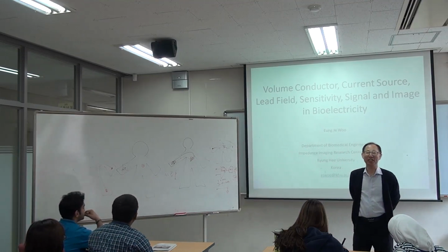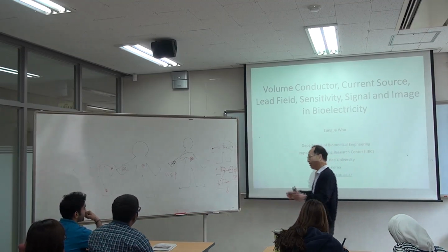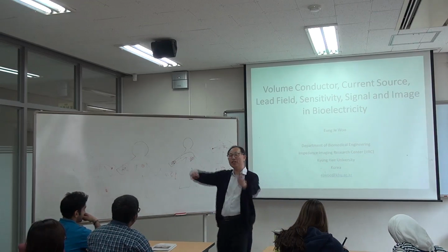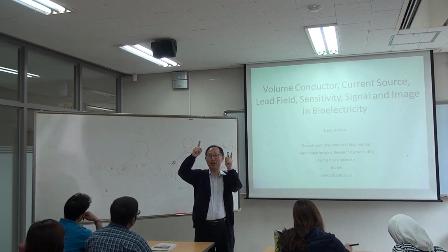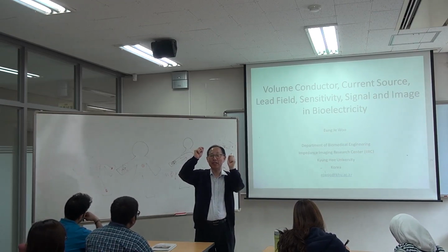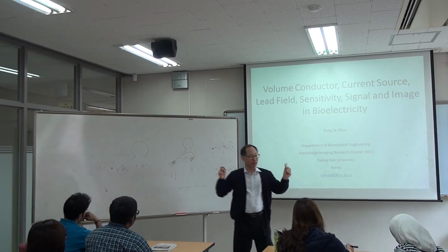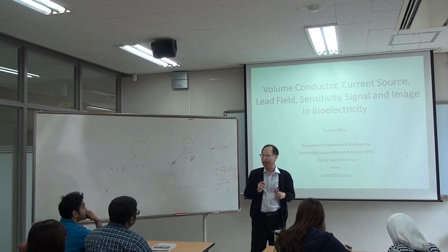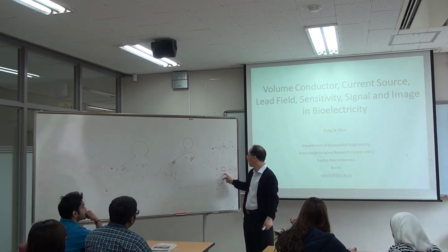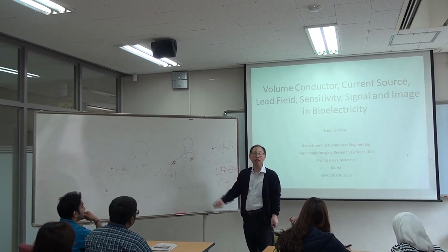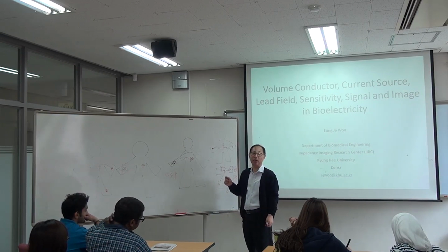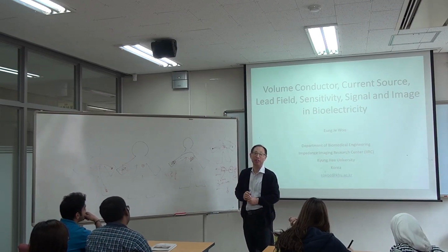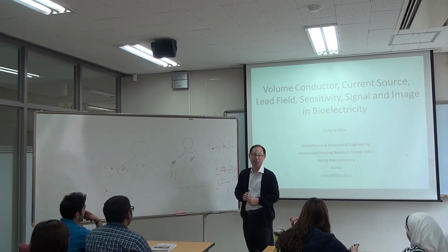Yes, yes. In order to measure voltage, you just need two electrodes or two probes all the time, because voltage is basically a voltage difference. The reason why they use at least 3 electrodes is that, for instrumentation purposes, it's better to make this amplifier a differential amplifier rather than a single-ended input amplifier.